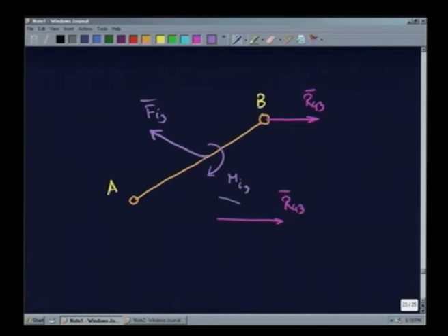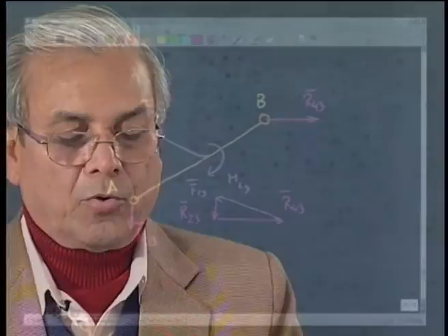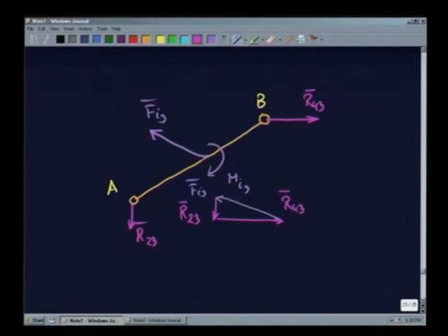So, you will find this is the inertia force. Then the force here has to be such that it closes this triangle, that will be R23, the force acting on this link from link 2. So, drawing the force diagram which has three forces here, the triangle can be completed and the last unknown force on link 3 at the joint A can be found out by this.